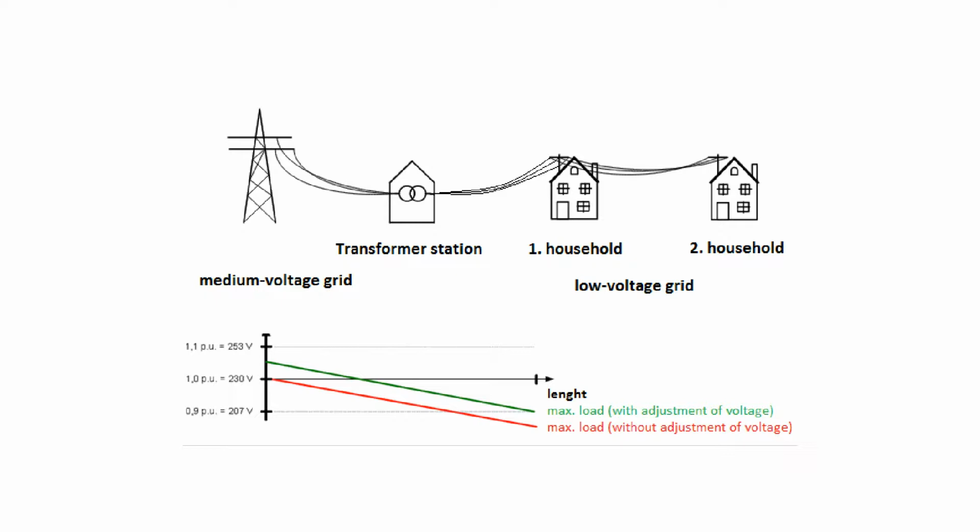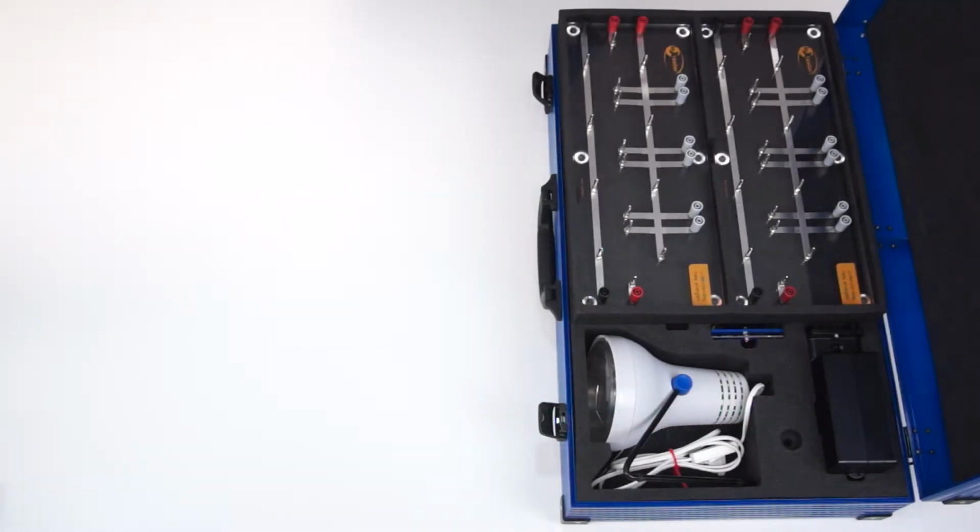In Germany, the nominal value of the voltage has been defined as 230 volts and may vary, for a secure supply, by a maximum of only 10% of this value. With the installation of private photovoltaic systems, it may cause overvoltage. We want to simulate this issue in a trial with the smart grid components.